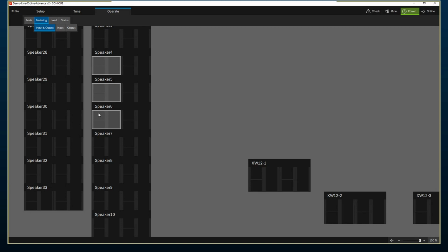And this would be the limiting. Depending on what kind of speaker and parameters were engaged in that preset, it would be peak anticipation limiters, the RMS limiters, and so forth. And this would be shown in yellow, and it would move from the top and then move down whenever the limiting was occurring. So at a quick glance, we can see all these parameters.